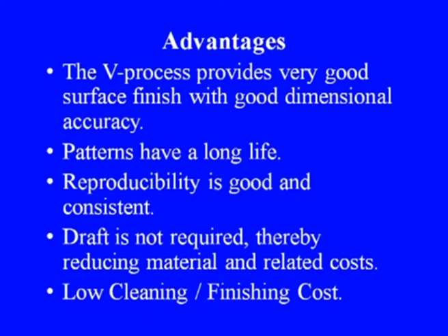Now, let us see the advantages of this V process. The V process provides very good surface finish with good dimensional accuracy. The patterns have a long life. Reproducibility is good and consistent. Draft is not required in this process, thereby reducing material and related cost. And also the cost due to cleaning or finishing is relatively low.